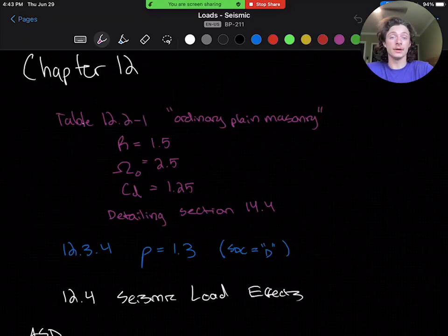Although this is not a building structure, we are going to design it under Chapter 12 as a non-building structure that is similar to buildings. Additionally, the cables are a flexible, self-dampening structure. We are not worried about the effects of seismic activity on the structural integrity of the walkway because of its dynamic nature and its flexible nature. Think about a building with a glass facade that could break under much smaller deflections than what the cables experience.